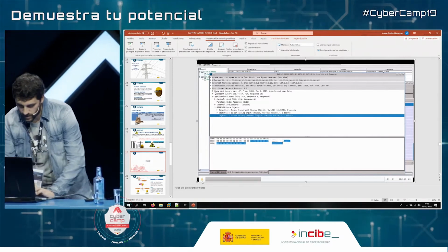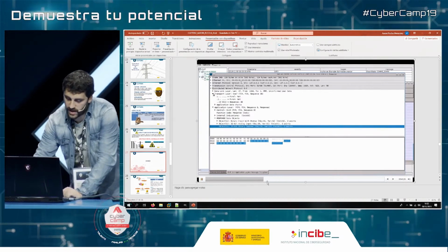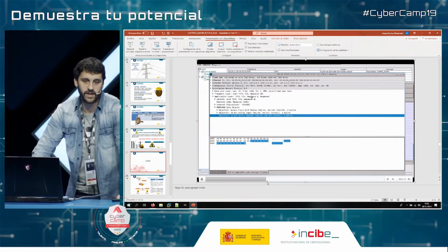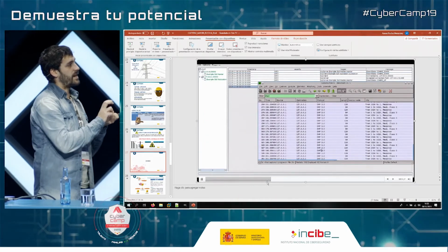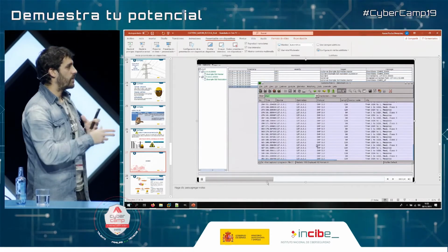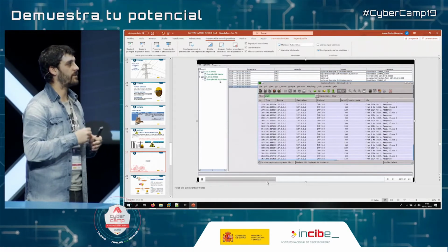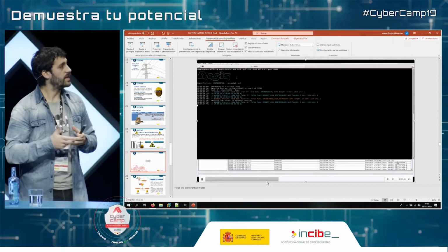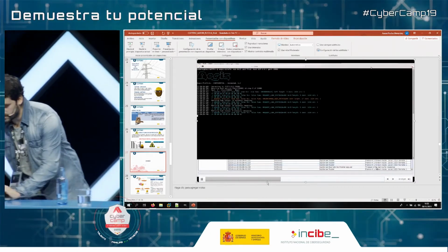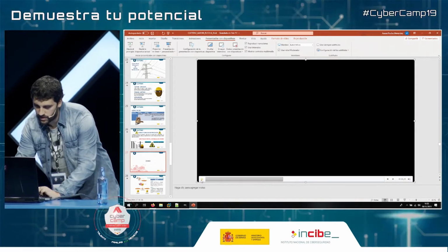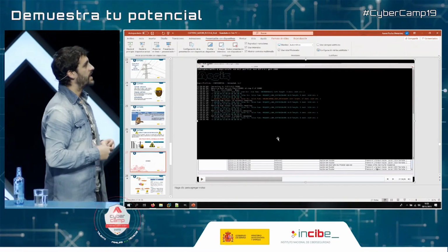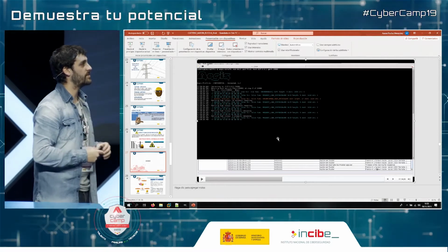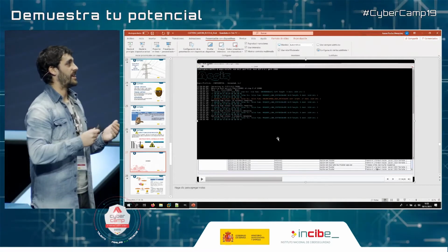So what are we going to do right now? We're going to try to use fuzzing techniques, which means that we're going to use different parts of the protocol in order to start changing values, so that there are modifications and many orders are sent. So here we used a fuzzer at the level of DNP3.